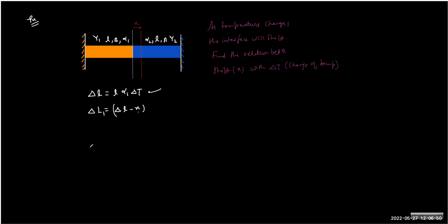Just a minute. Now coming back to the thermal expansion of the second rod. It can expand by value L alpha 2 delta t. Correct? Yes, sir. This is the free expansion. But not only you prevented the expansion, you compressed it further. So the delta L2 is how much? Tell me.